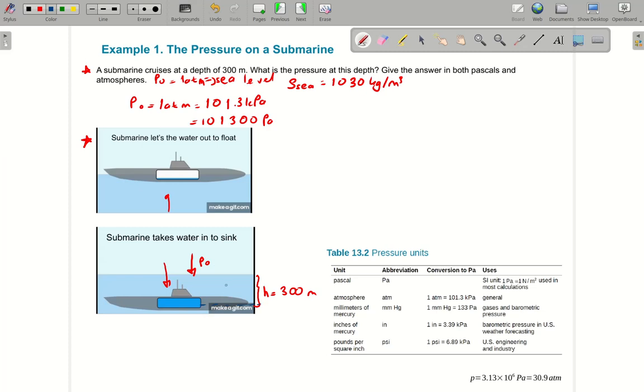It will be this pressure plus the pressure of the water, right? So I'm going to call it P water. This thing alone would be the gauge pressure. Remember, the pressure of fluid alone will be rho G times the height, H or D. I call it H in this case. And rho is, the fluid is now water, so rho will be seawater. That's called gauge pressure. Again, just to keep the terminology here. But we're looking for the total pressure, so we'll look at P0 plus rho GH, and that's all.